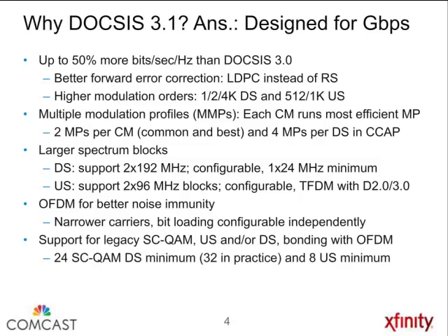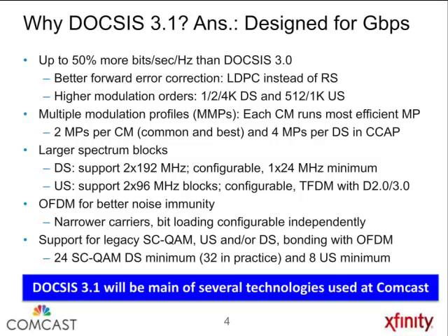And then the support for legacy single carrier QAMs. A very important part of DOCSIS 3.1 is the development of backward compatibility. So legacy single carrier QAMs will be supported by DOCSIS 3.1, so that, for example, if we wanted to, we can deploy CPE and only use it with DOCSIS 3.0 downstreams and upstreams, or we could deploy the head-end equipment and only support 3.0 upstreams and downstreams, or support 3.0 and 3.1 upstreams and downstreams. This all relates to the backward compatibility, which I will expand on in a later slide.